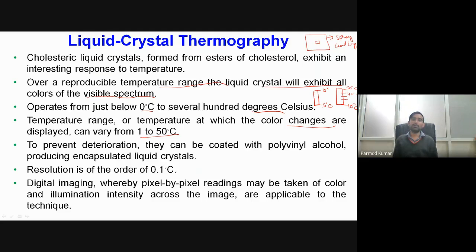Okay, so what we will be doing is taking the photograph of the surface where we want to measure the temperature, and then we will relate that photograph to our color scale, that is, corresponding to what type of color we have, what value of the temperature. Okay, that we will relate using nothing but our image analysis. And as in image analysis, if we have a high resolution camera with which we have taken this photograph, we will have a very close spatial contour of the temperature profile.